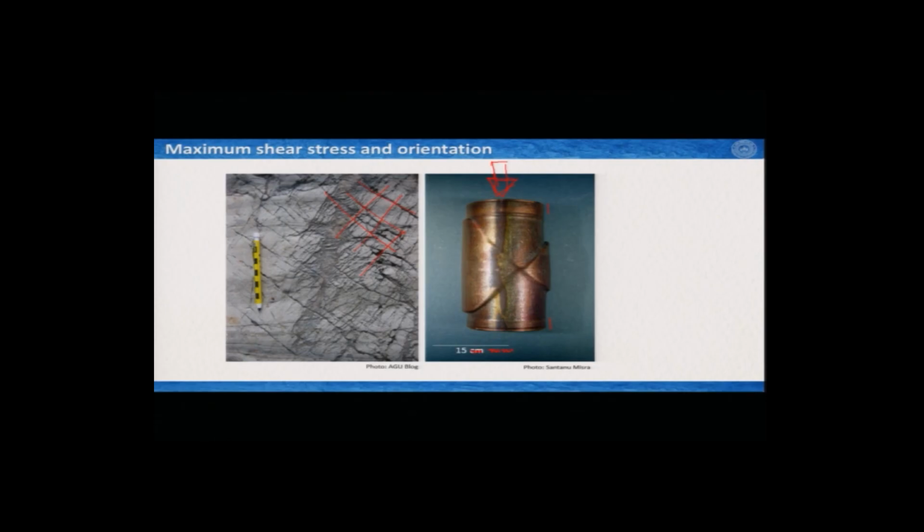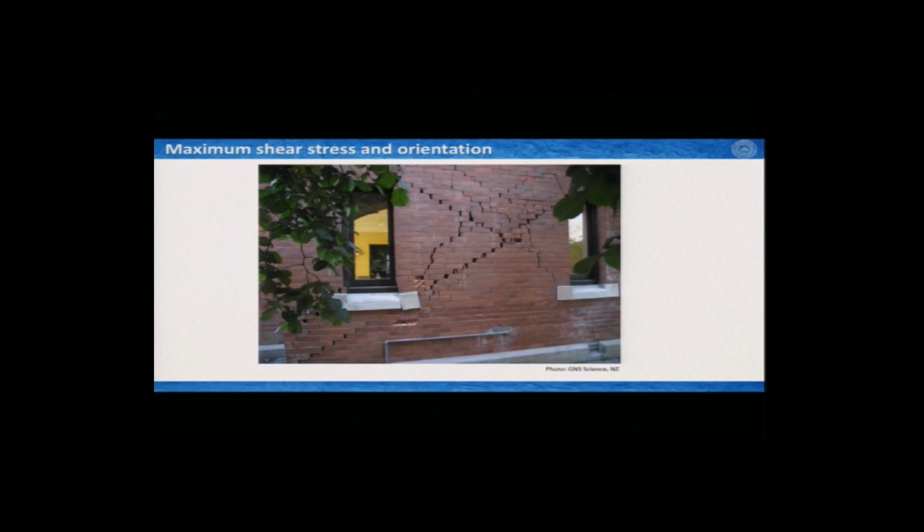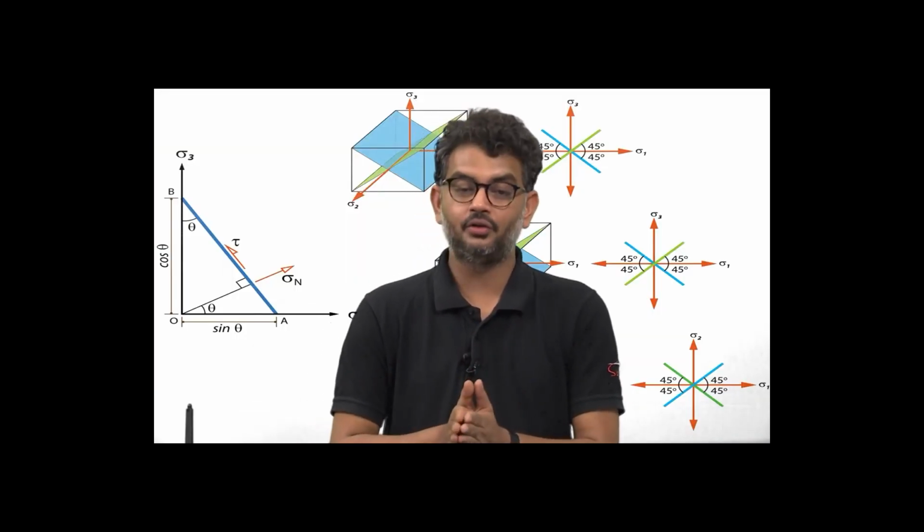And then what we see, because of the compression we generate two sets of fractures. They have some sort of displacements which we are not looking at right now, but we see that this must be the intersection of two principal axes of stress, and we know this is the compression direction. So, if we calculate, this must be the acute and this is the obtuse angle. Now, we see it also in a very different way. We have learnt it when we have an earthquake, that there are two different motions, or you can resolve it in two different motions.